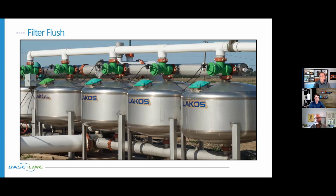And then, as you mentioned, because the base station 3200 is also managing the irrigation valves on site, if it weren't managing the backflush, the water source would essentially shut down in order to backflush the filter. Meanwhile, the irrigation valves are running, and the controller could potentially have a low flow alarm because the water source basically turned off while the irrigation was running. Okay. So it is becoming more important to have one brain on the site controlling all of the water and filter flush cycles like this, so it can operate correctly without sounding false alarms.